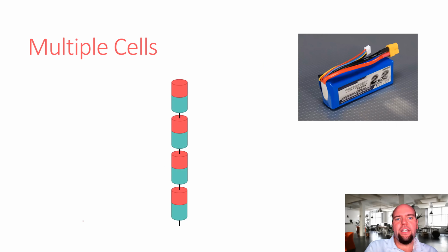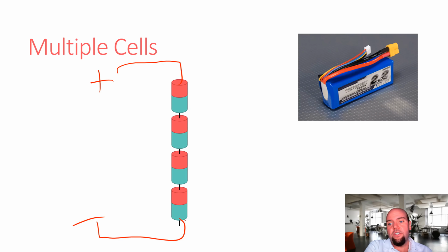One issue is, what we'd like to be able to do is just apply a big voltage here, and charge all these batteries up at the same time. But as we mentioned, if you do this once, you charge this up once, and one of the batteries had a slightly higher self-discharge rate. So after you fully charge the battery, one of the cells wasn't quite fully charged and the others were a little bit overcharged.